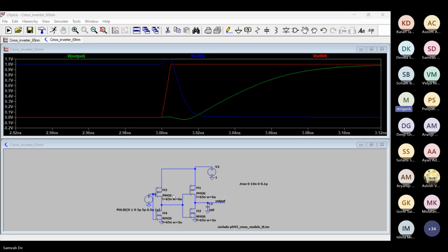Yes. So then what is the question? That gives you the answer, right? So there is a net capacitance. Even if you don't have an external one, there is a capacitance because of the parasitics, and that is included in the model itself. The MOSFET model has all those parasitic capacitances. If you just look at the model text file, you will find some of the capacitor parameters mentioned.